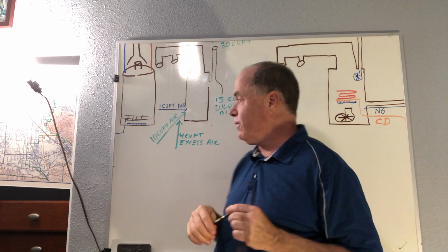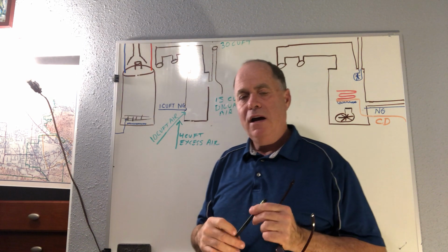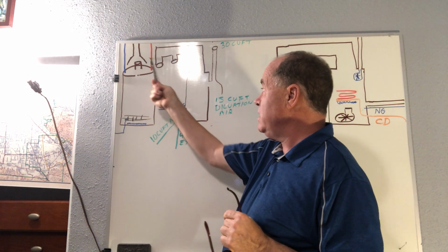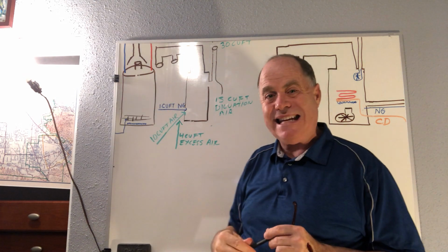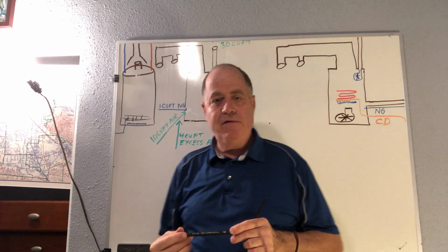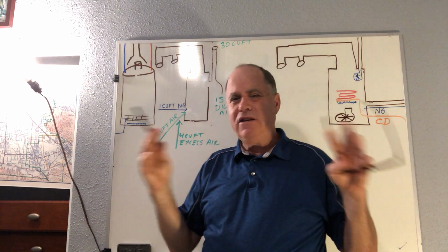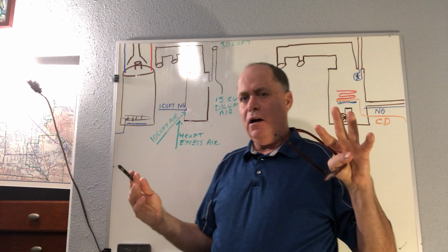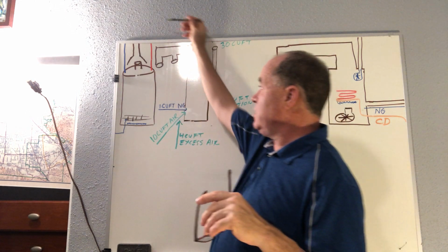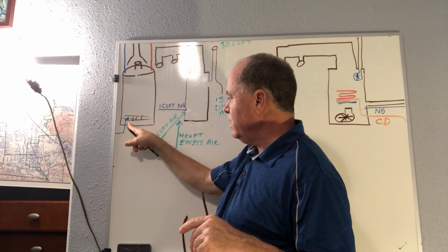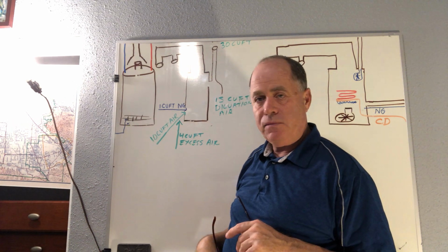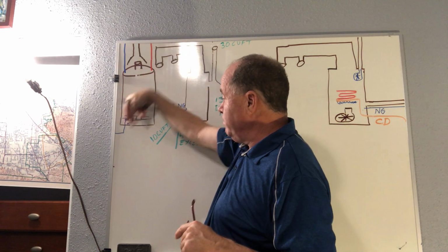Let me also talk for a minute. I didn't mention the point. Another reason for the draft hood and this kind of design for these natural draft heating appliances is to prevent downdrafts. Wind is a weird thing, and if you got a wind going down here, when you're down to just your pilot light, the wind can get down and blow that out.